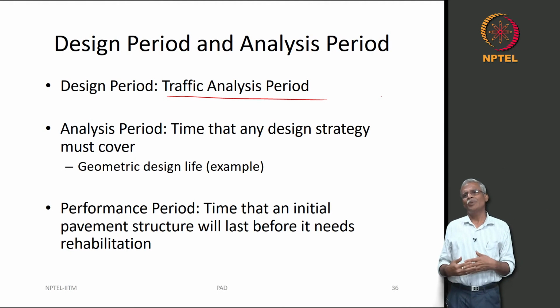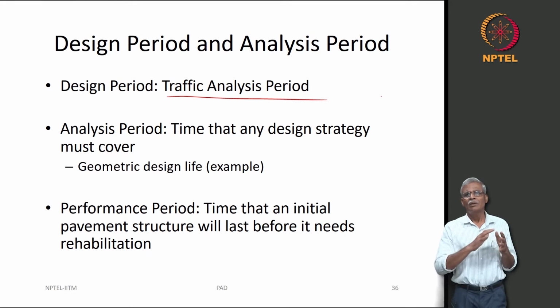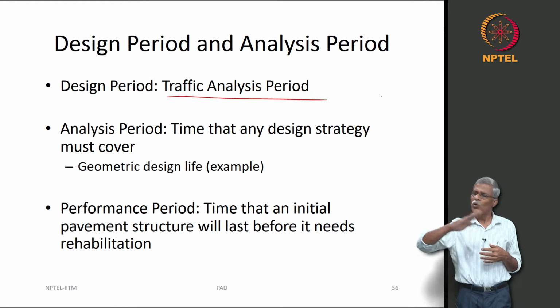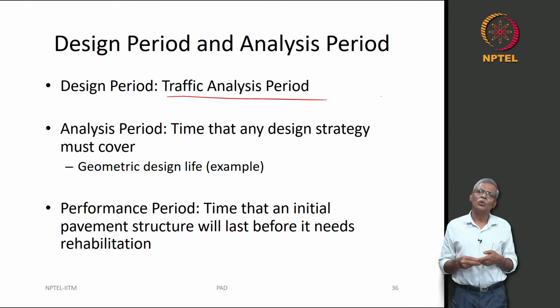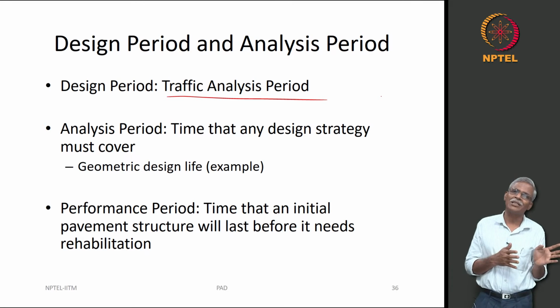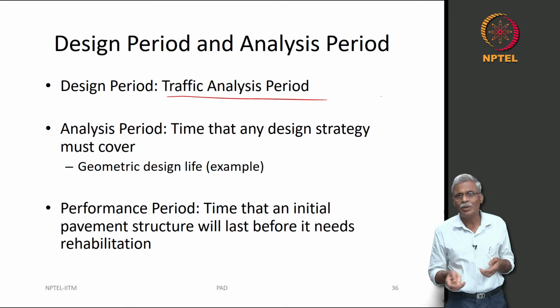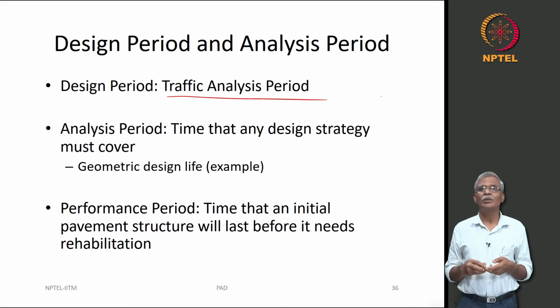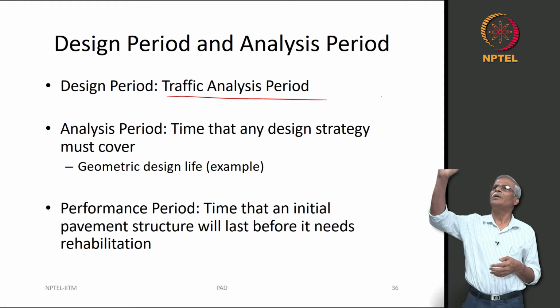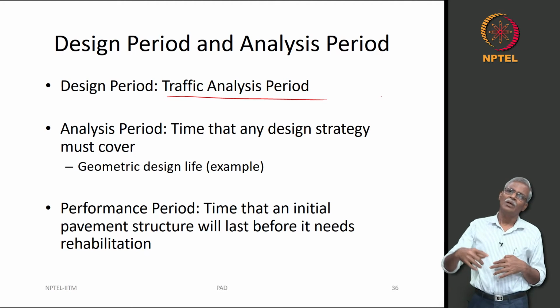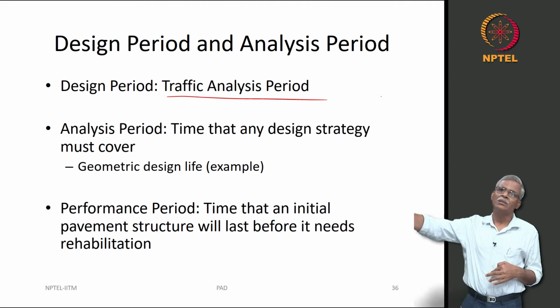Now you have high speed trucks, in fact many of the trucks that we have in our country are very good, they can go up to a much higher speed. Now what will you need to do is to make corrections in the highway. Is it really possible? It may not really be possible, because you have designed something for 80 kilometer per hour. Now if you want to elevate it to 120 kilometer per hour, you need to make major corrections in the